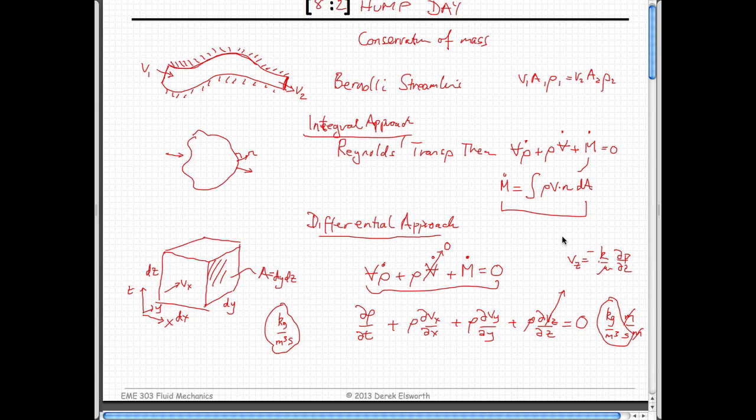And this is really a statement of the amount of head losses you have in a system. You have to apply a certain pressure to be able to move fluid. So intrinsically, this is kind of equal to the head loss thing that we have. And so the bottom line is that you can use expressions that you get, which you will use. It'll be the diffusion equation, and if you're doing Geoscience 452, you'll talk about this in terms of hydraulic conductivities and specific storages. If you're a petroleum engineer, you'll talk about this in terms of fluid pressures and compressibilities of fluids. But this is the expression that you ultimately use to substitute Darcy's law into.